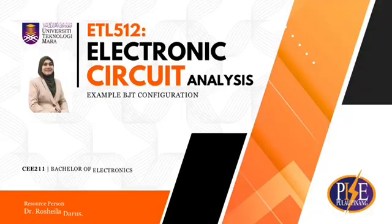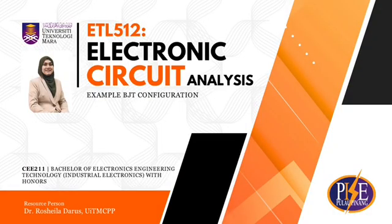Welcome to ETL 512, Electronic Circuit Analysis. Today, we're going to look at an example of a bipolar junction transistor, or BJT, in the common collector configuration. We will go step by step: first setting up the circuit, then replacing the transistor with its hybrid pi model, and finally calculating the input impedance, the output impedance, and the voltage gain.